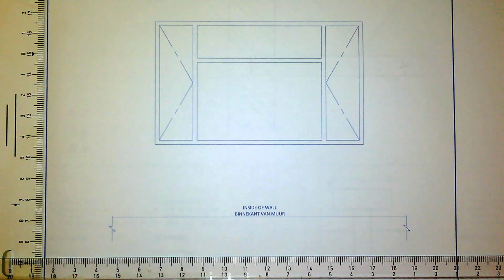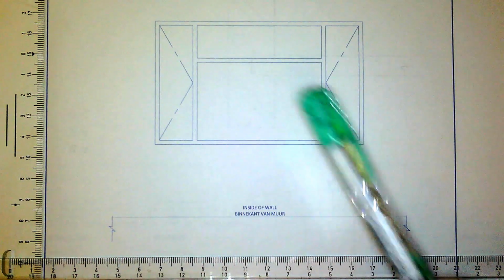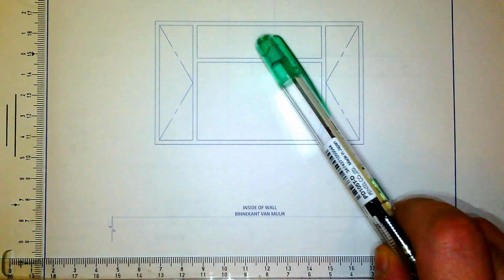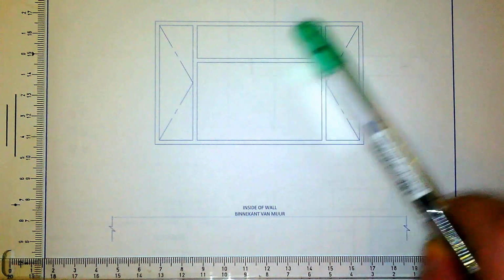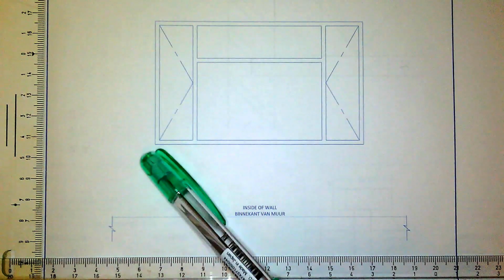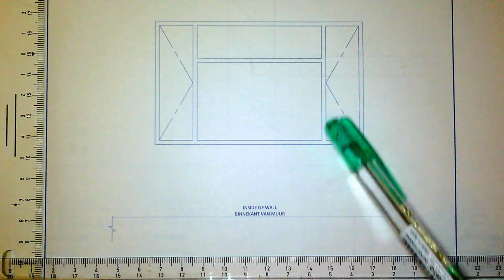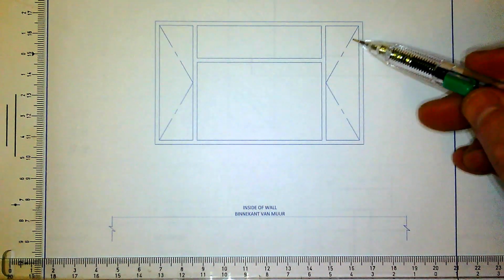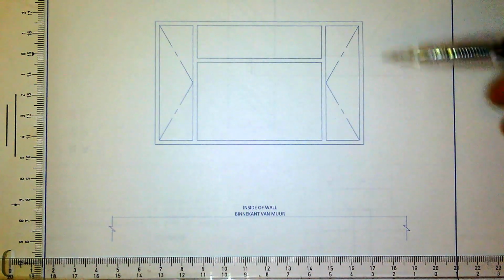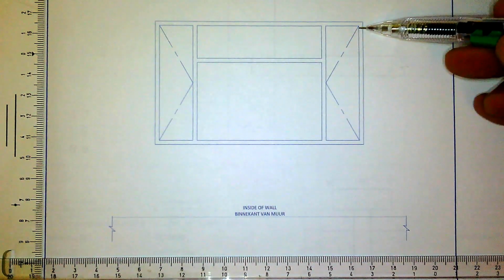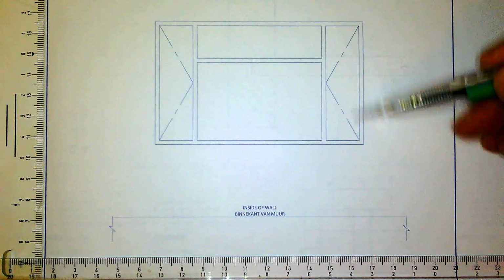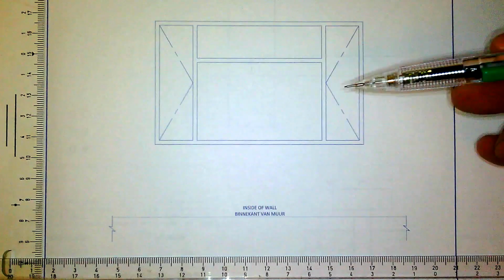So on page 10.5 on the left side, here we are given a window design. So we've got two fixed glass panels here. There's a slight frame going around with the window. Okay. And then the parts on the left and right side, this broken line here indicates the swing of the door, or the window I mean. So the hinge would be here on the right side and the window would swing open towards you.